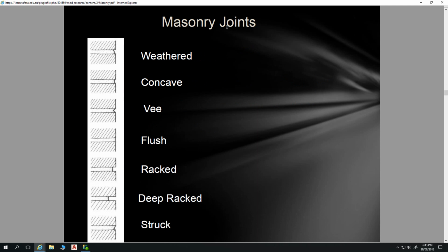So as you're building your brick wall, you've got your brick, and you put mortar on here like that. You trowel on there, and then trowel some on the end. Put it on and squish it up a little bit and nestle it in, and then you bring your trowel along and scrape off that little bit of mortar that's on the outside. So you end up having pretty much just a flushed joint like that. But then when that mortar has gone off and stiffened enough to be raked out nice and neatly, typically this is what you do. You do a raked joint.